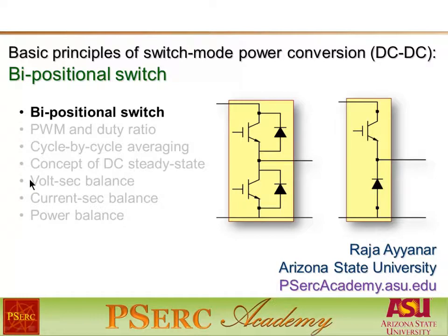Then we will study the three important principles which are valid in steady state, namely the volt second balance for inductors, the current second balance for capacitors, and the power balance principle. In this video, we will begin with the bipositional switch.